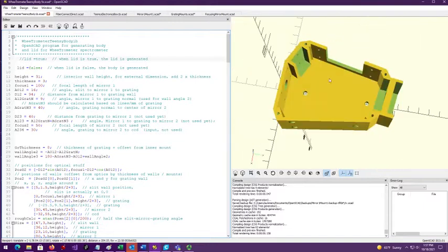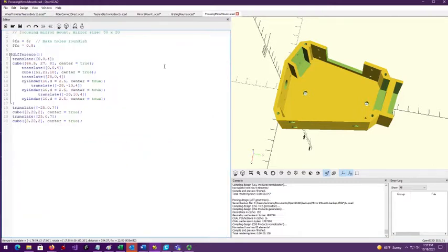So the grating fits into this little green square over here. The inner body mount, it goes up against this wall. The grating goes between the inner and the outer grating mount, and then you screw it in from the back, and that holds everything still. By changing that angle inside there, you change the angle at which the light comes off and strikes the focusing mirror over here.